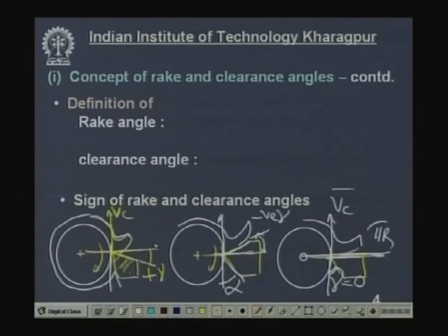Positive means lesser force, less stress and all these things, less temperature, but if the rake is positive and large, then the tool becomes very thin. If this rake angle is very large, then this tool edge, the wedge angle will be very small and it will be mechanically weak. So, to strengthen the tool mechanically, we use negative rake, particularly when the tool material is brittle in nature.